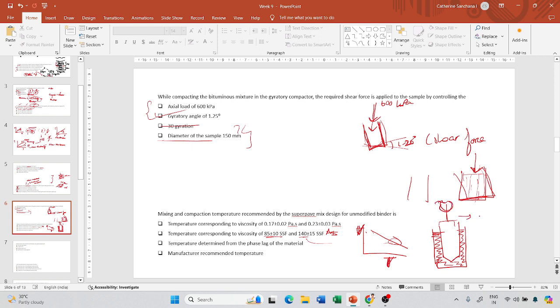From this rpm you can find out the shear rate, okay? And in order to rotate the spindle at this particular rpm, the instrument has to provide a torque to this spindle, right? And based on what the sample is in between the cup and the bob, if the viscosity is high, then a higher torque will be required to rotate the spindle, okay?